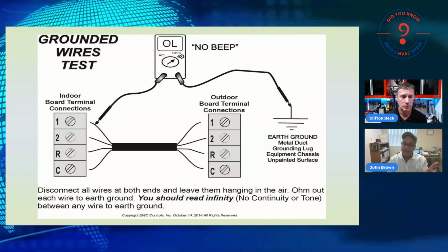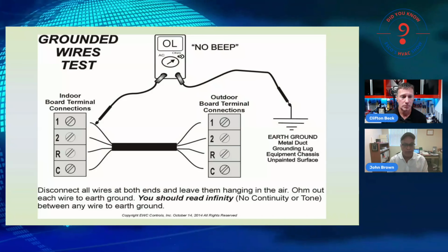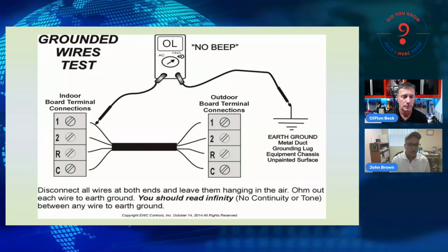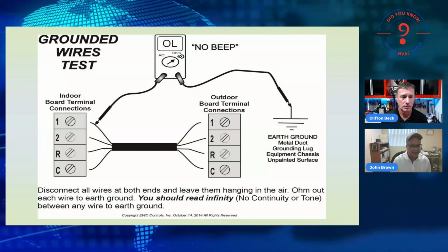Once again, infinity, no tone, no beep. I should read infinity, every wire in that cable to earth ground. That's a good second test.